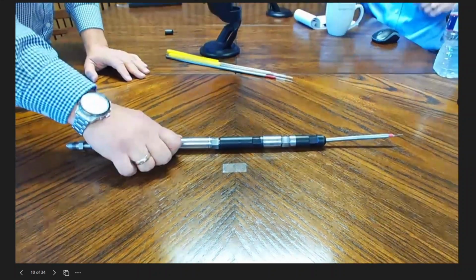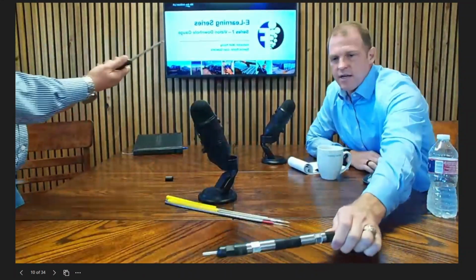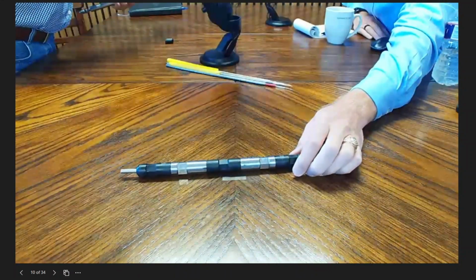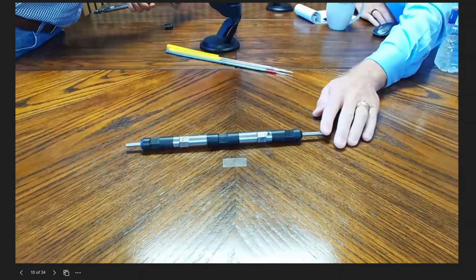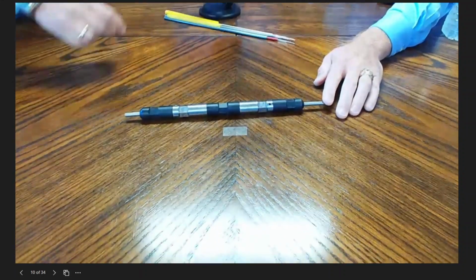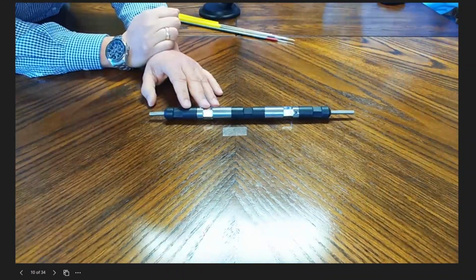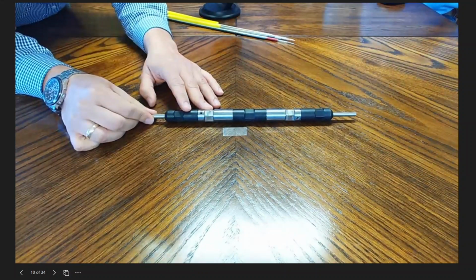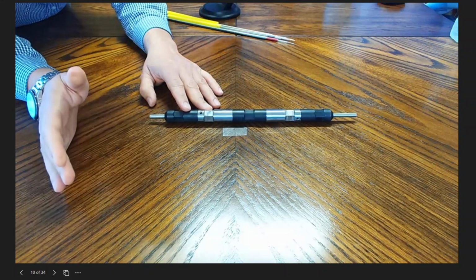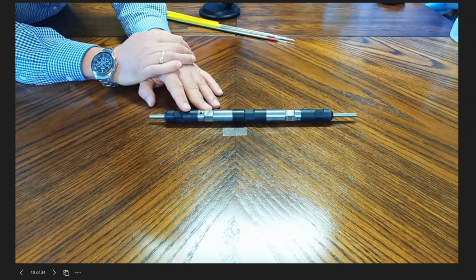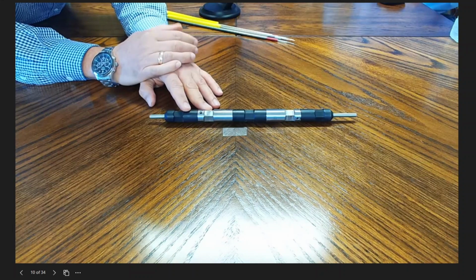Okay, that makes sense. And so that's the cable head, and that attaches the cable head to the gauge itself and communicates that TEC cable to the gauge. Yes, and here we have what we call the cable to cable splice. The downhole cable goes from the gauge all the way to surface in parallel to your production tube. So in a 10,000 foot well example, you would have 10,000 feet of TEC cable run across that production tubing. Yes, sir.